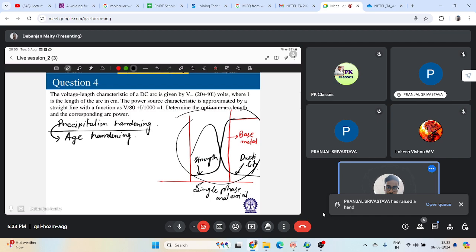And over here also the strength within the melt boundary will be too low, but immediately adjacent to the heat affected region, the thermal cycle, basically you are doing heating and then quenching, and if you are doing some age treatment, that aging process will recover some strength in that weld region. The material beyond this region is only overaged.